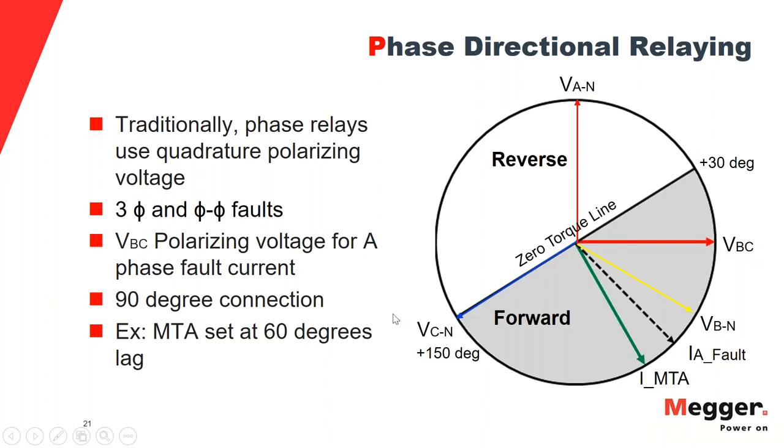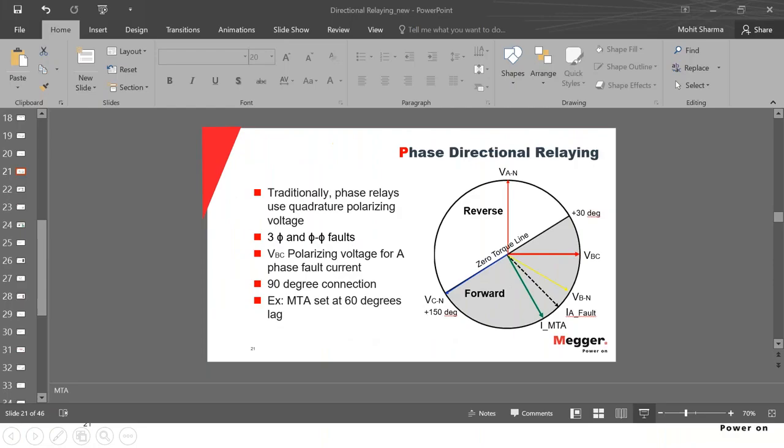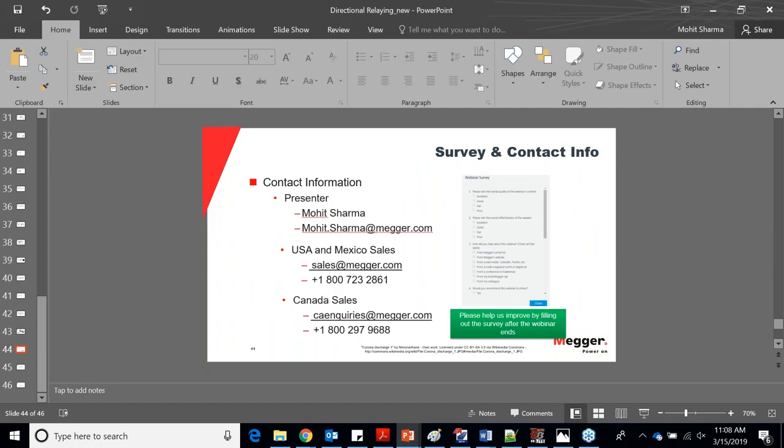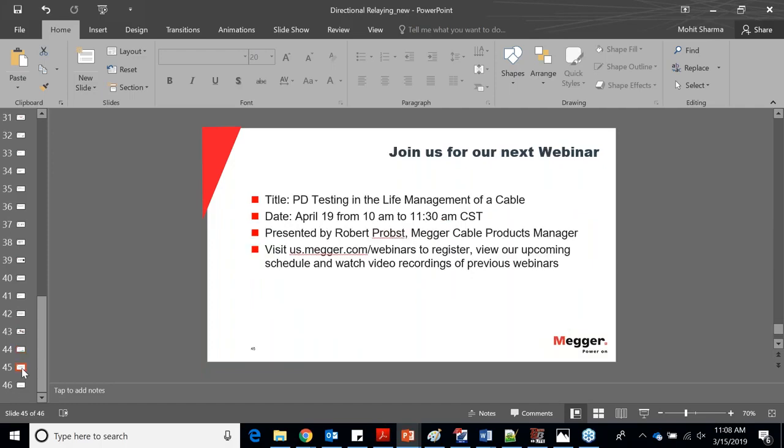All right. The next question is for Danabal. Can leading power factor currents, especially at low power factors, spoof directionality? It's a good question too. It depends on when the directional elements are used in generator protection. The possibility of mal-operation is there. So we use reverse power functionalities to avoid this leading direction element operation. It is possible sometimes in generator protection relays, but in line protection, no, it's not.